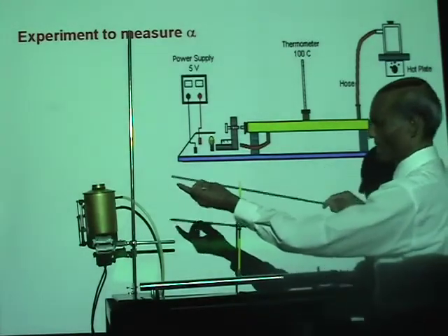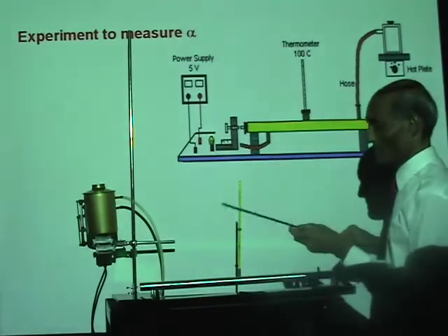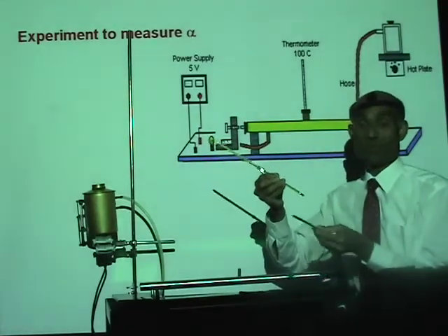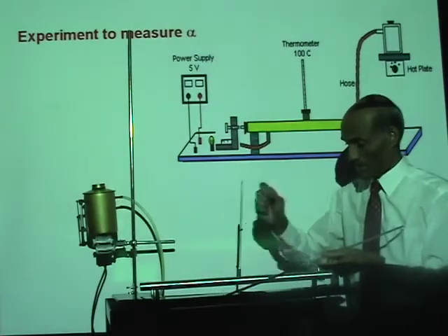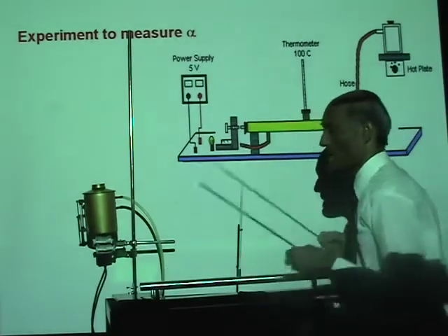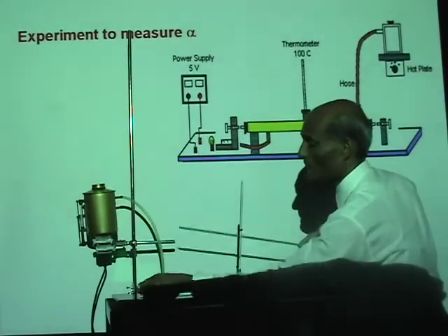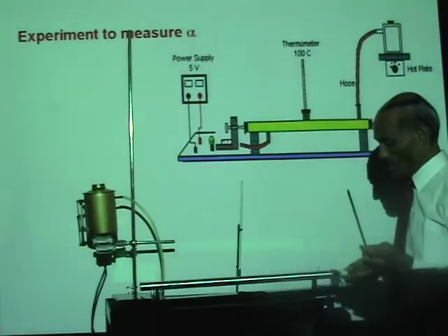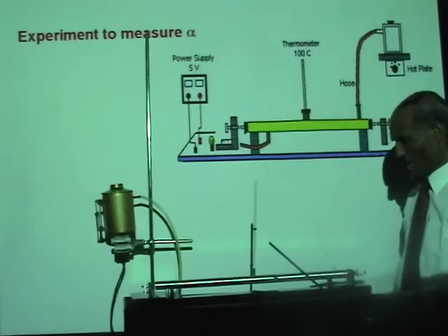is this. Now, first you measure its length L0, and then measure the room temperature, that is your T0. So measure the length L0 at temperature T0, and then insert this into the steam jacket so that one end of it is in contact with that screw there. In other words, it cannot expand that way. Now, we have a micrometer screw gauge arrangement here.